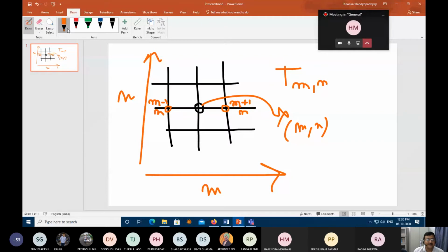Now I can also define two other points, which are the neighbors. Here I have graduated to N plus 1, and this remains M, because I did not change my x. And this becomes N minus 1, and again remains M. So if I can calculate this point from these four, and if I can do this for all the points in an M by N array, I am really able to get the heat transfer that is calculated here. This is the starting point of the whole system.